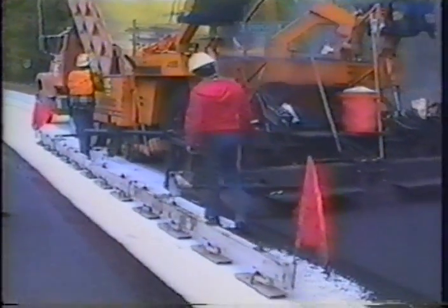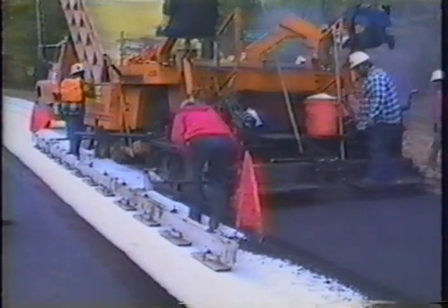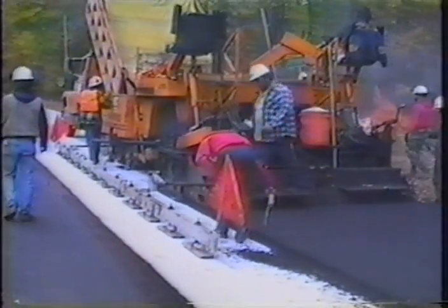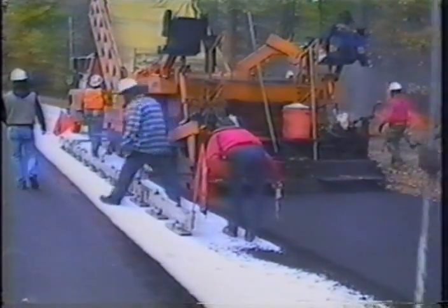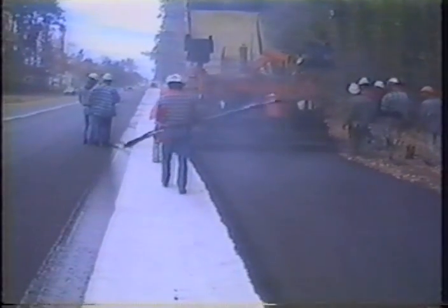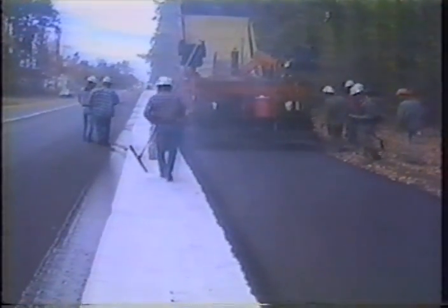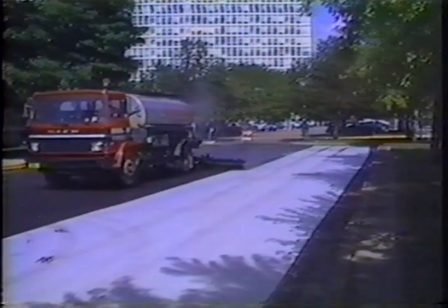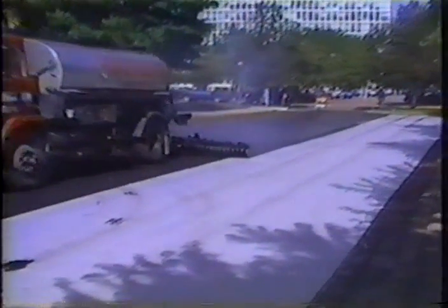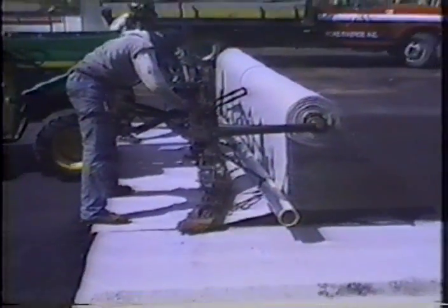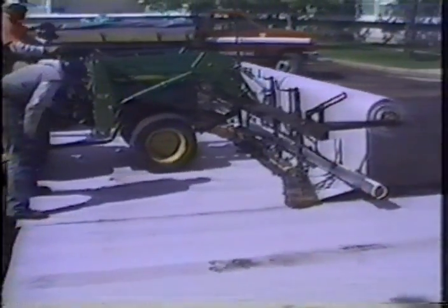Overlays are traditionally used to cover cracks and provide an improved driving surface. However, a chronic problem is that old cracks reflect up through the new surface layer. Geosynthetics do not prevent reflection cracking. However, they can retard it in two main ways: by waterproofing and by local reinforcement. If properly sealed with a waterproof coating, non-woven geotextiles can inhibit the infiltration of surface water.